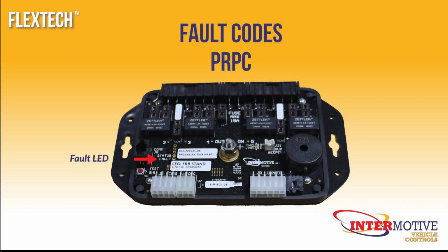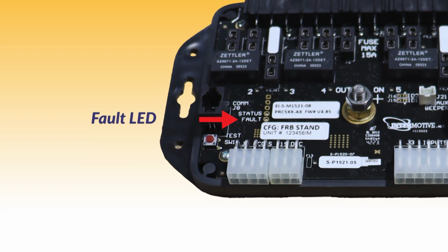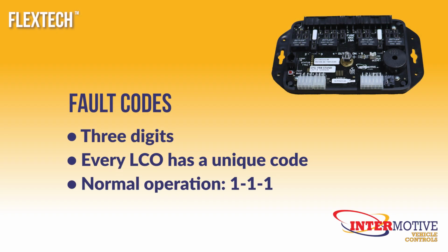Below the status LED, there's a fault LED, which indicates the current highest priority fault. Fault codes are 3 digits. Every low current output in the system has a unique code. In addition, there are fault codes for LIN communication. For normal operation, the LED will slowly flash 1, 1, 1, which means status OK.